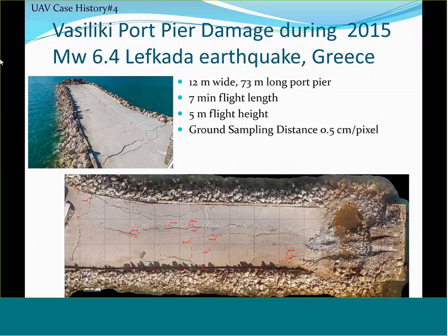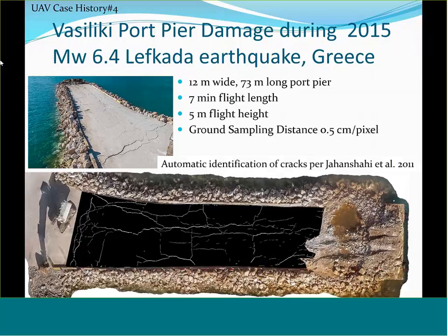And an output of that is essentially an orthophoto and a 3D point cloud, of course, but an orthophoto that you can actually use to measure any type of width of the crack that you want, and that is shown there. But I think what we will see in the future is not just manual dimensioning of the cracks like we're doing here, but if Kevin clicks one more time, we can use automatic identification feature recognition techniques.